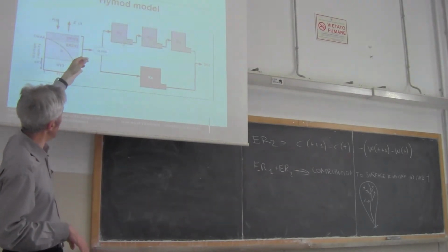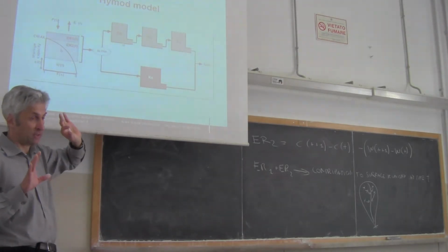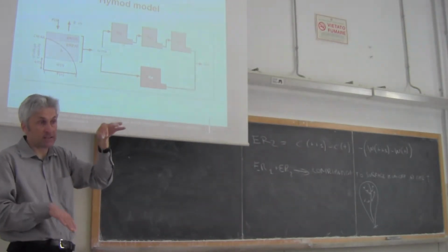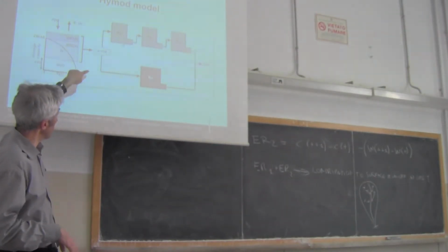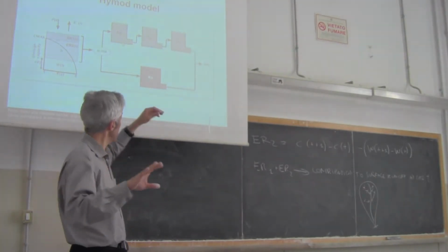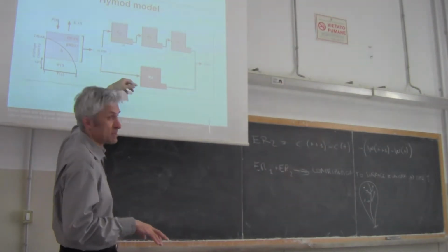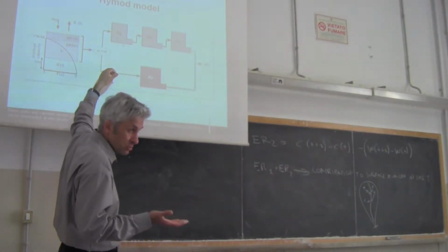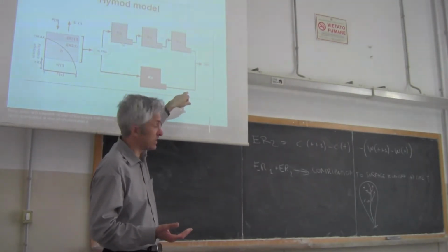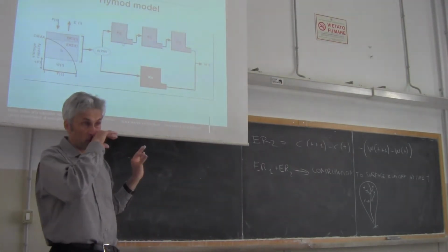So basically, through alpha, you split the surface runoff in two components, and if alpha is 0.5, it's split in two equal parts, and one contribution is routed through a linear reservoir, which you know already. So the inflow to the linear reservoir is alpha times ER1 plus ER2, and then the outflow from the linear reservoir is considered to be flow to the closure, river flow at the closure.